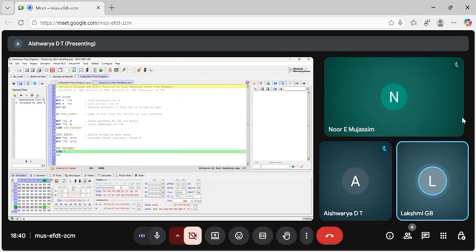75H is 00. After execution, OV flag set, division by 0 occurred. 76H is 0, error. 77H is 0, error.